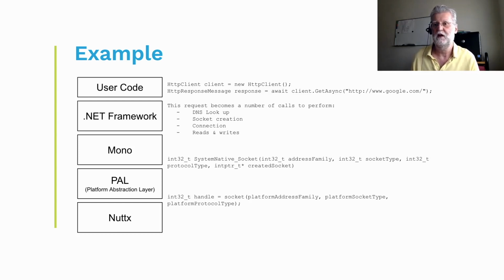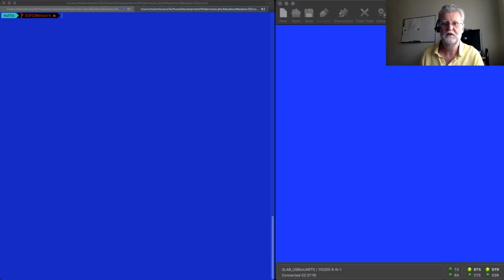So now let's have a look at a demonstration of that low-level system in action. So I'm just going to switch over to the debugger system. So on the screen now, you should see two distinct windows. The window on the left is the command window, which I'm going to use to fire up GDB to start talking to the STM32. The window on the right is a serial connection made through to the STM32 and will allow the STM32 to give us status messages back to us as the application is running.